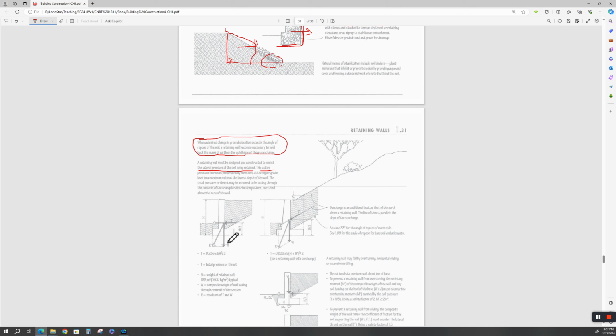All right, so all these are force vectors, and he's talking to you about where the center of gravity of the force is, which is 1/3 of the height of the wall. So 1/3 the height is the theoretical center of gravity of the force that's being pushed out that way. Now also, this is trying to turn this thing around. It's trying to make it rotate about the base. That's called a moment. And we have a gravity force. And this little r vector is the resultant force.